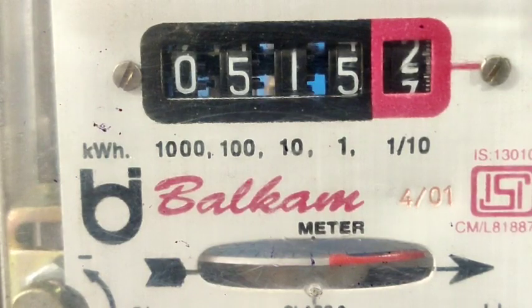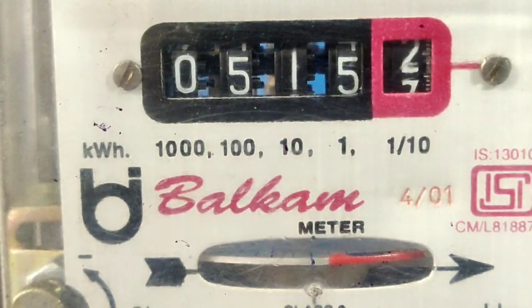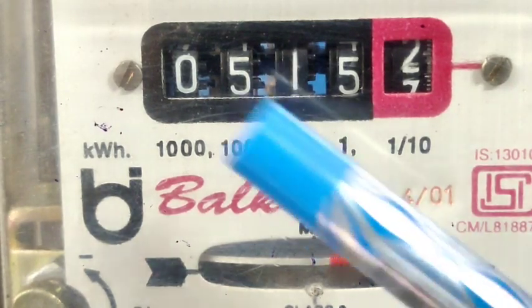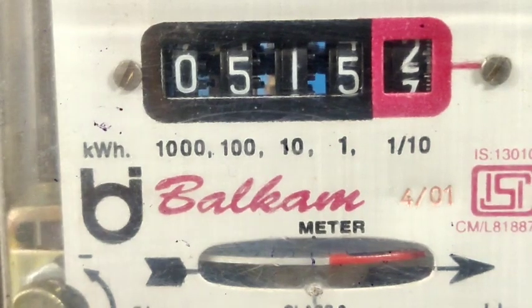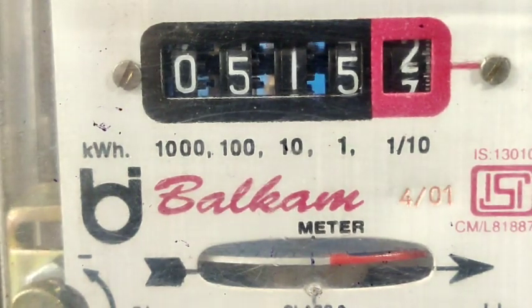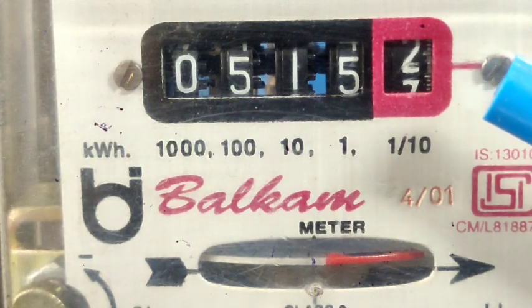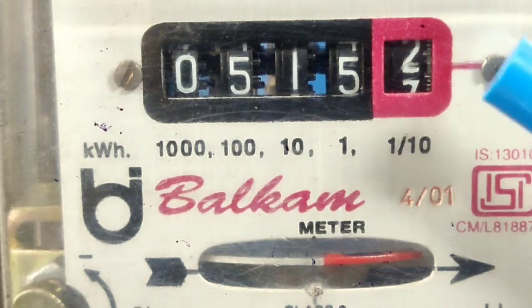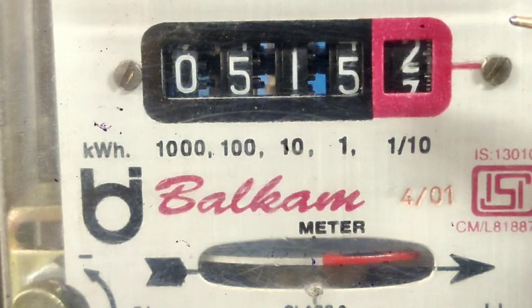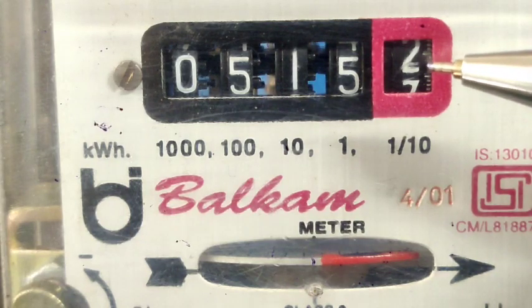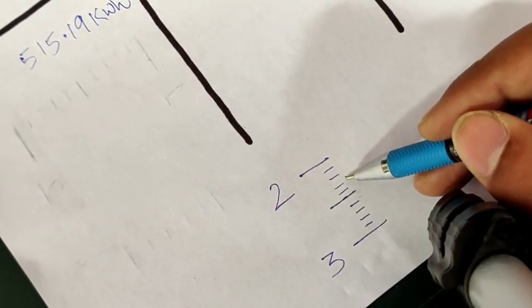So we have turned off our load, and we can clearly see here that our meter reading has changed. Alright, so let us now find out the value of kWh2. Here you can see that 515 has remained the same because we have not turned it on for a longer duration. So there is just a slight difference in the reading. But now the red marker here is not between 1 and 2. It is now between 2 and 3. To be more precise, the red marker is corresponding to the third division between 2 and 3. Meaning that your red marker is somewhat here.